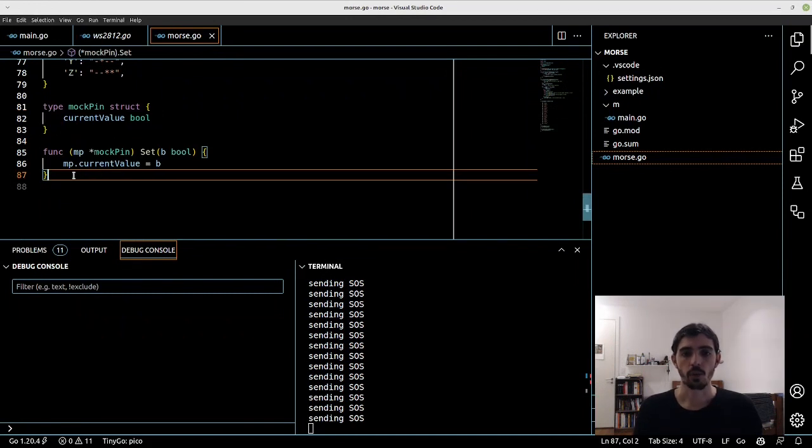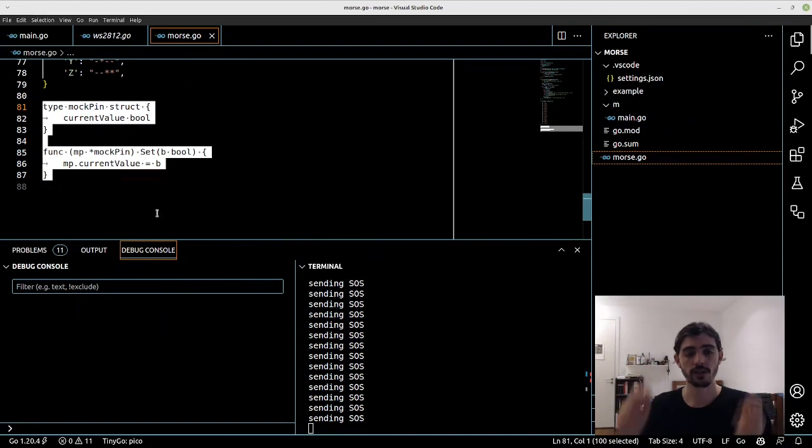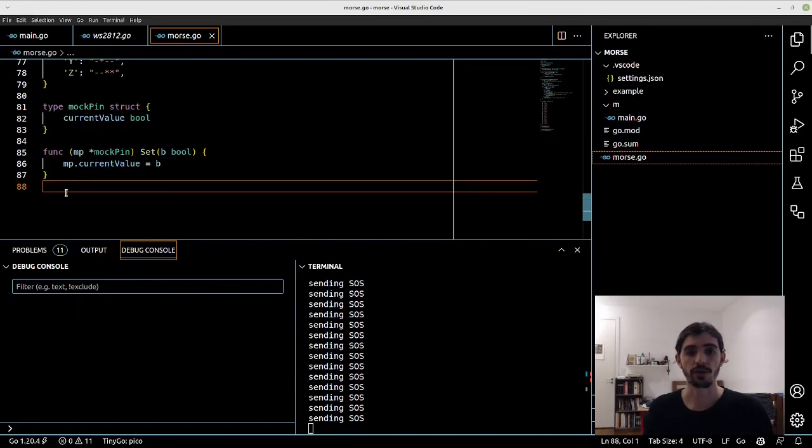And we can play with these. Maybe we have access to some hardware and not some other hardware during development, and we can decide which parts of our system we simulate with these mock hardware abstraction layers, and what part of the system we actually use real hardware for.